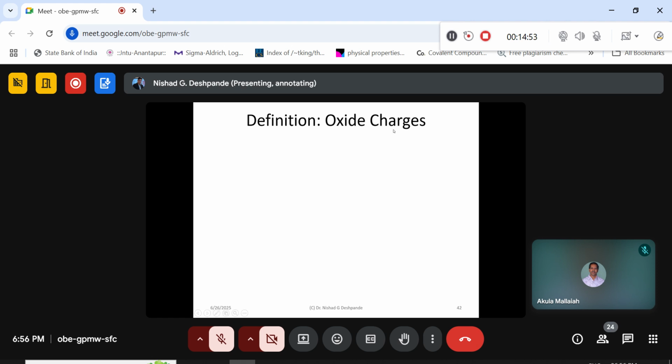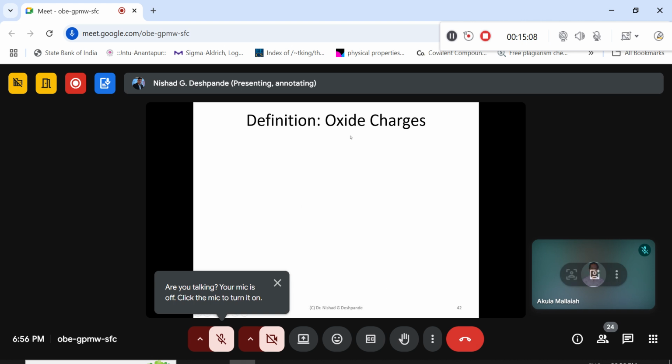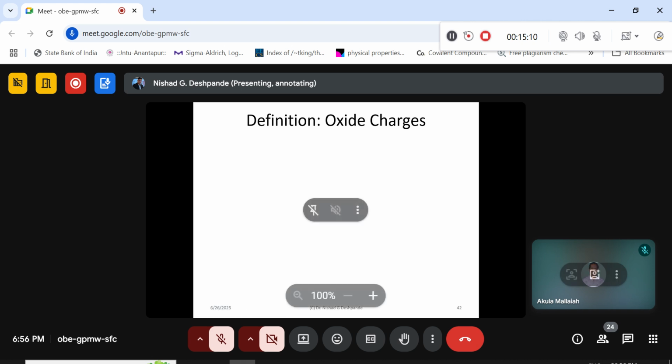In VLSI, thin oxide layers of say 20 to 200 angstroms are very much in demand, because that is where the thin oxide growth processes mostly take place. Secondly, we have discussed dry and wet oxidation processes.